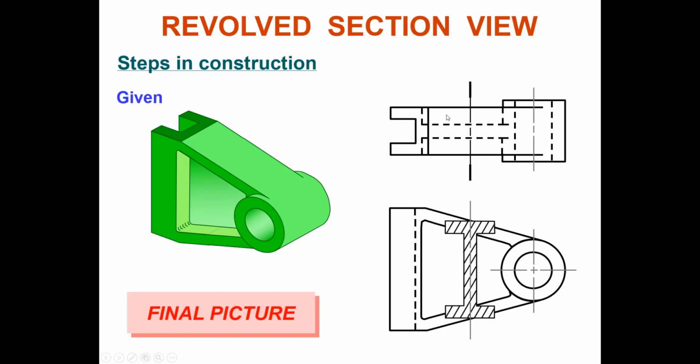Okay, I didn't say top view. Top view, of course, typical orthography. I'm talking about front view where you do section line, no hidden line. Broken out section, only the region you do sectioning, no hidden line, but the rest of the region, hidden line. Same goes for revolve section. Nampak tak kelas? We have hidden line. Clear? You understand what I'm trying to explain to you? Ini ada hidden line. We have. Clear tak? Yeah, clear. Understand?